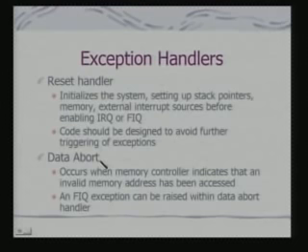The data abort exception occurs when the memory controller indicates that an invalid memory address has been accessed. That means there may not be physical memory located at that address, and when such a location is accessed there has to be an exception, because that is an error condition. So a data abort is an error condition, and I need an exception handler as part of my operating system to take care of it.